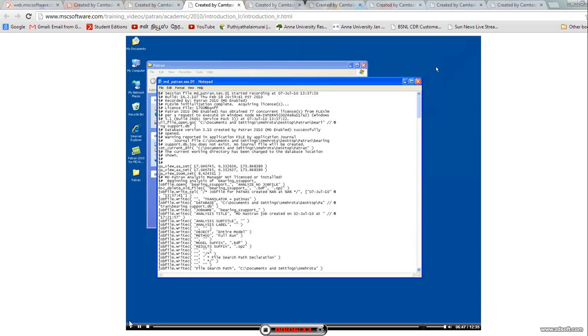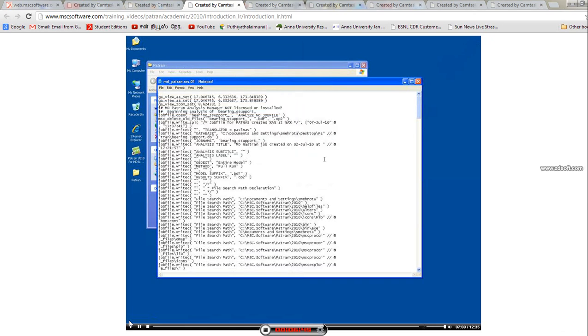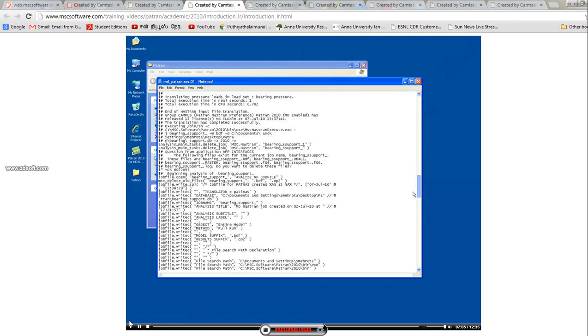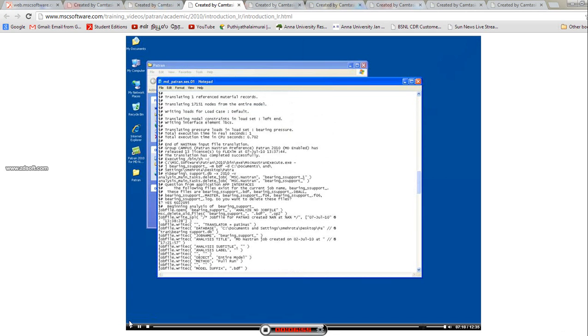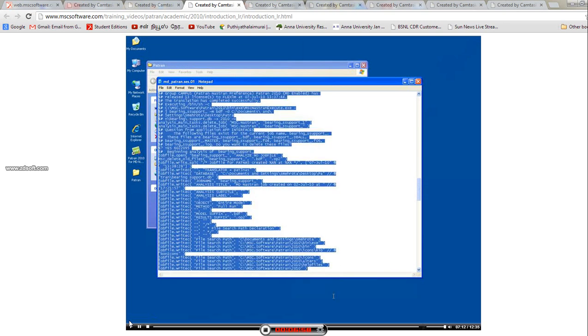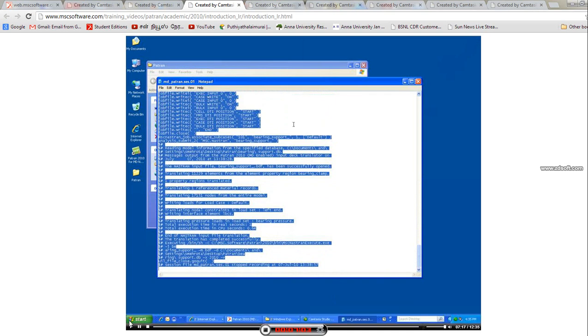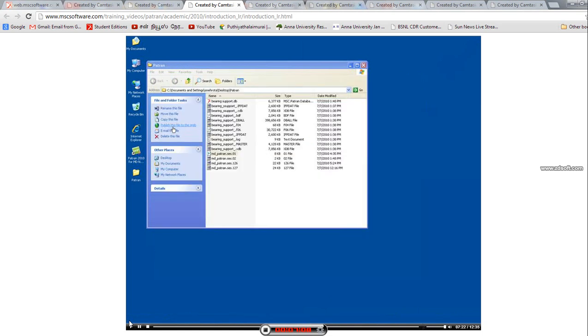If I play this session file as it is, it's going to ask me to replace all of my files, including the database file. To avoid that, I'm going to edit my session file by removing the first half and also removing the analysis part. Save the file and then close.